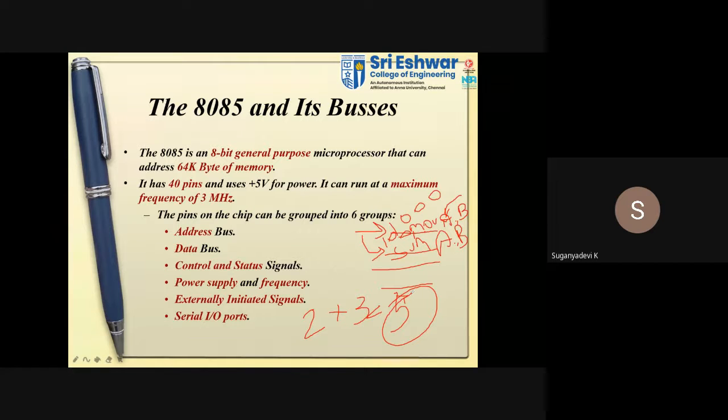In this case, I'm going to move the data content from B to A. If you take a single data, say 2, without 3, and it is present in B, I'm going to move this 2 to my accumulator. The copy of data will be moved from the B register to the accumulator. Only a copy of the data is moving, not the exact data; it does not vanish from the B register. The 2 remains in the B register as well.